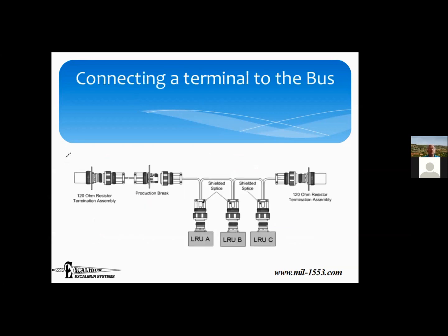Okay, now in terms of connection to the bus, again, different buses use different methodology. Ethernet uses a switch as the way you connect to a bus. In CAN bus, you actually just kind of twist your wire onto the bus. Now, obviously, there are smarter ways of doing it. And the spec defines termination resistors.